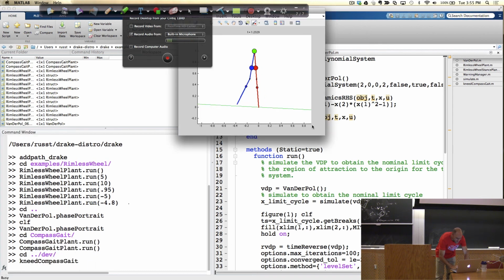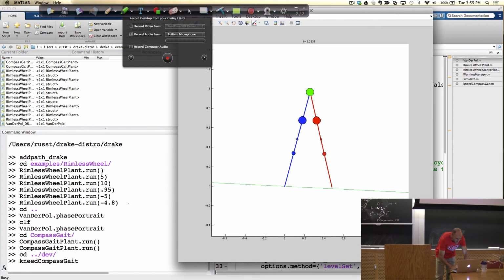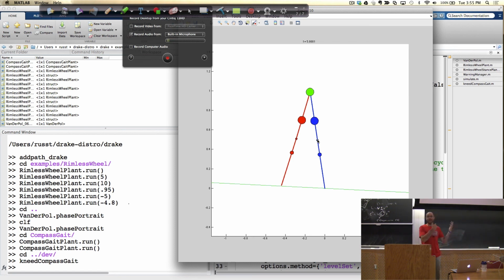You can even do it with more legs. If you put a knee joint at the hip, now this one has an extra collision which happens at the kneecap, and that's essential for the dynamics. Not only do you not want your leg to be swinging around just like a quadruple pendulum, but this one actually has a collision event. Energy is lost at the knee strike. Energy is lost at the collision, and then it keeps going. But this also has a stable limit cycle behavior, which you can exactly understand with the Poincare map analysis.